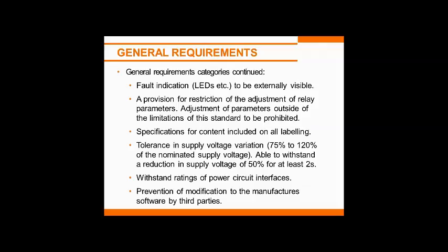So our relays these days tend to be 24 volts DC, which means that they should be able to run for at least 2 seconds at 12 volts, at 50% of that. And most of them, or all of them, do, certainly the ones to the latest standard. Withstand ratings of power supplies, etc. Once again, just the ability of the relay to withstand any voltages it's likely to get on.